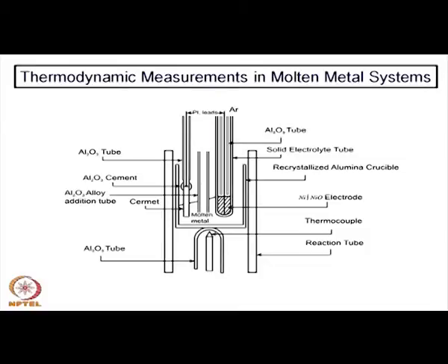So, for the dissolved oxygen or some other oxygen potential, there will be a thermodynamic equilibrium and certain oxygen partial pressures are normally available. Sometimes it is very important to measure those partial pressures for different purposes, and this is another setup by which one can use zirconia as an oxygen sensor, for measurement of oxygen concentration.